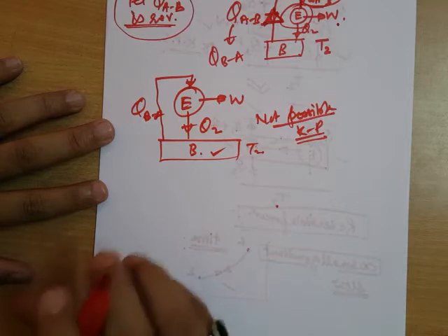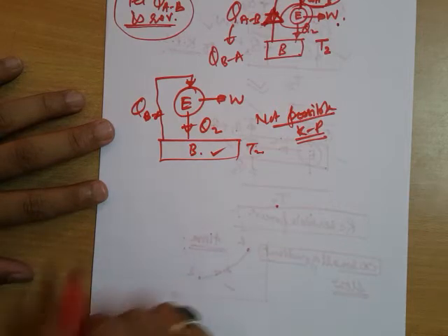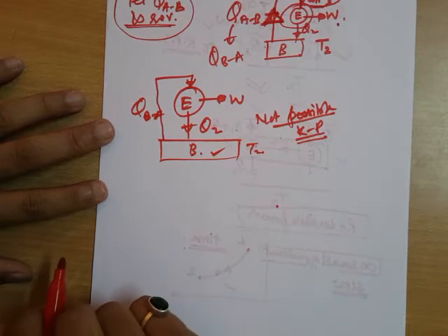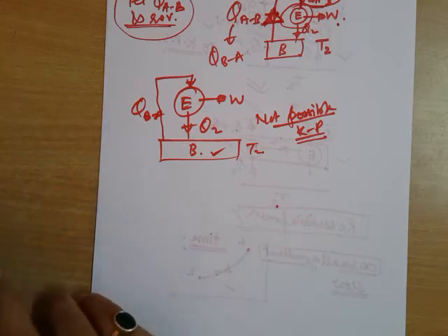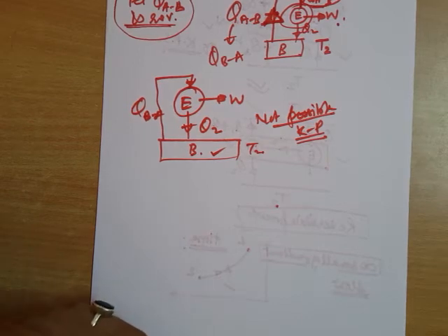He has to reduce this temperature gradient to an infinitesimal, infinitely small temperature gradient. And for that infinitely small temperature gradient to transfer heat, the time required will be infinitely large. And that infinitely large time will qualify that process as a reversible process.